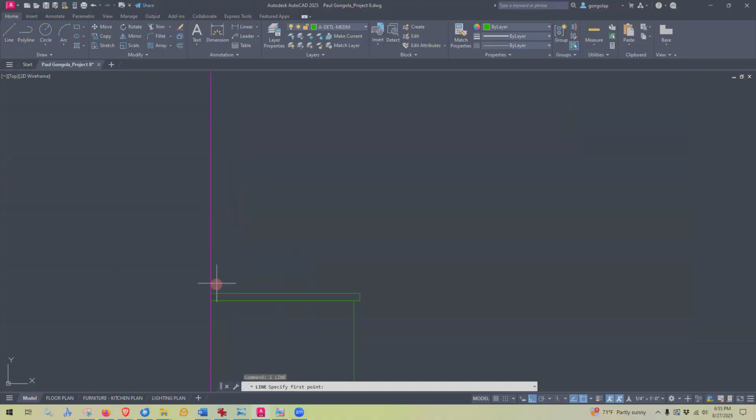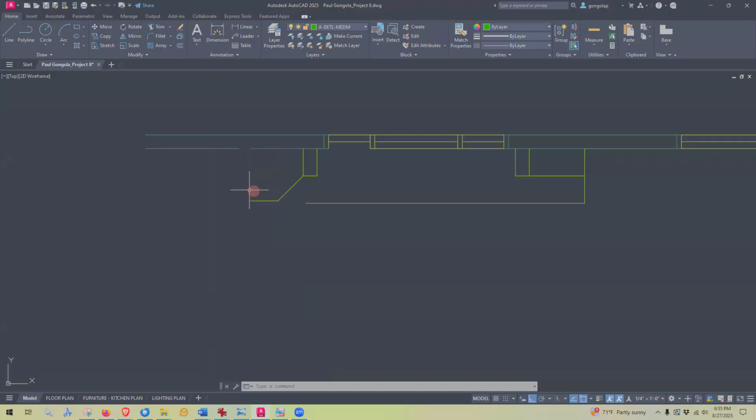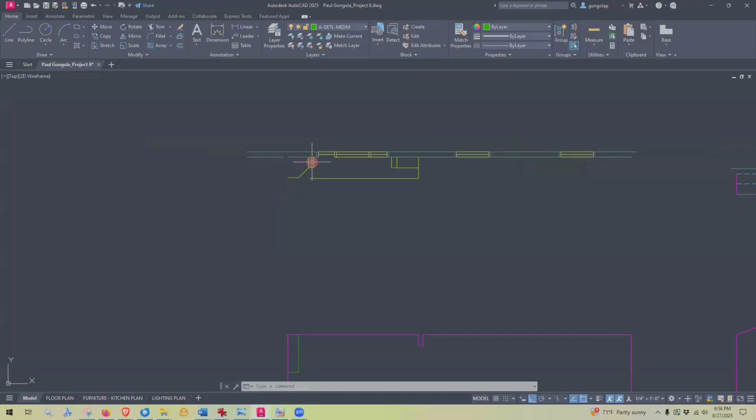So with my line tool, I will start here at the countertop, type 'top', O-track up 1'6". There is the bottom of my cabinet, and it extends out 12 inches or a foot. And I'm going to bring it right up to the ceiling. Good. So now I've got the corner cabinet and this little shelf over here. And if I look at my elevation over here, here's that corner cabinet, and here is that little shelf.